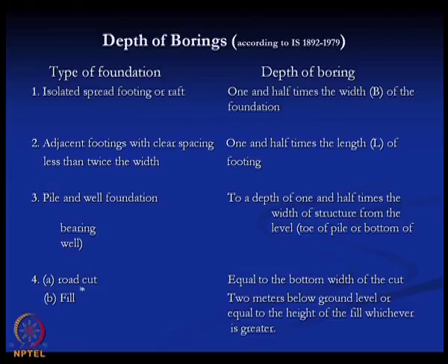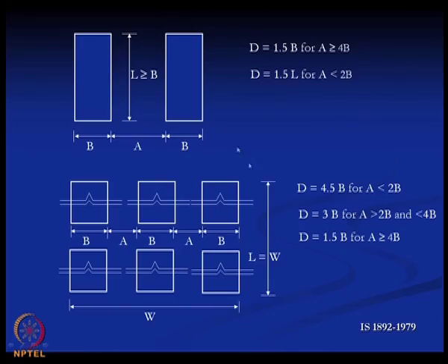Then the next one is the road cut, where the depth is equal to the bottom width of the cut, and then fill: if it is a fill, then 2 meters below the ground level or equal to the height of the fill, whichever is greater.